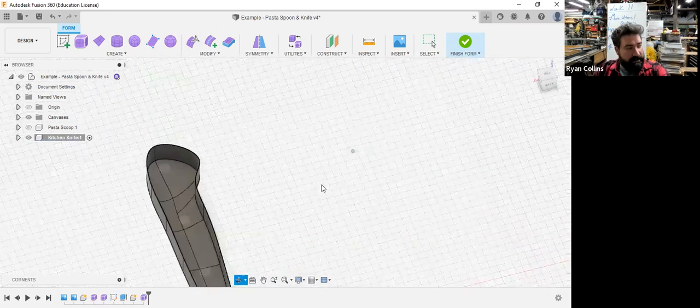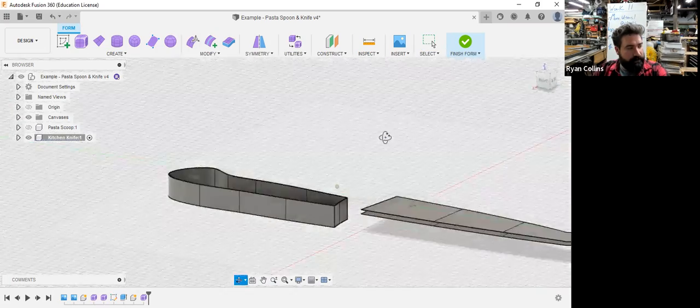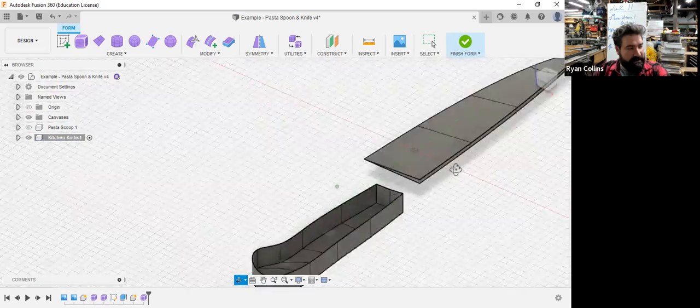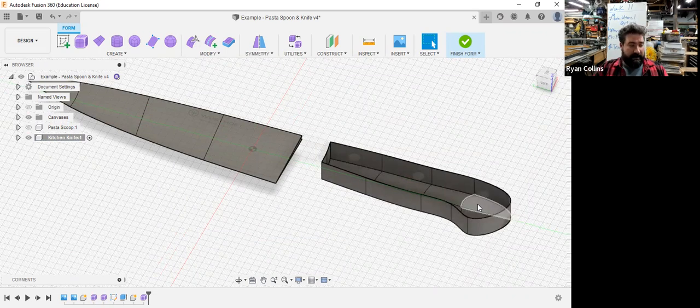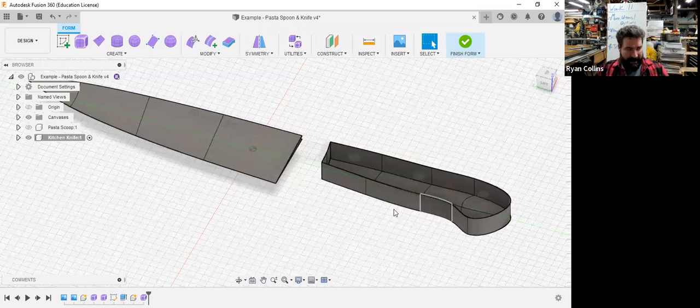I used an extrude, but look what it did. It basically created a box. The reason for that is it's a kind of true extrude. It's moving the faces I just chose down and creating a direct extrusion there instead of the rounding out.